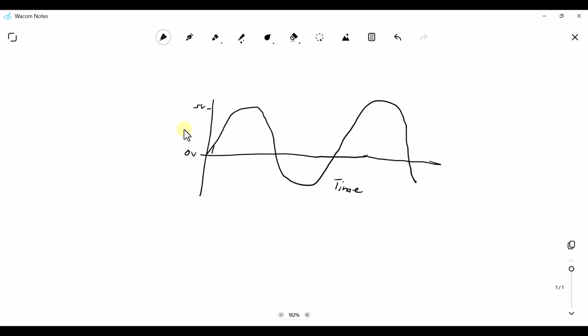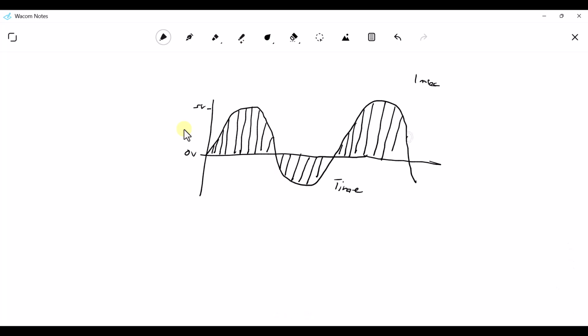So these are the samples that I am taking. Instead of continuous lines, we are taking discrete values of the analog signal. And this is what we call sampling. So let's say that the digital system, at every 1 millisecond, will take a sample of the analog signal that is entering it. So these are the samples that we have. Instead of a continuous signal, we have taken samples.